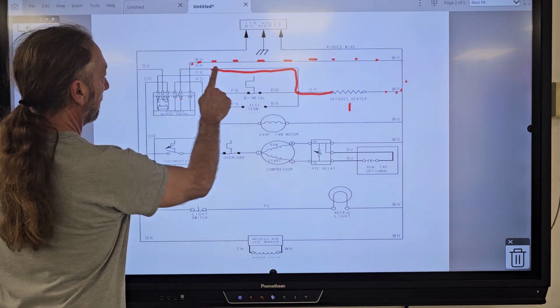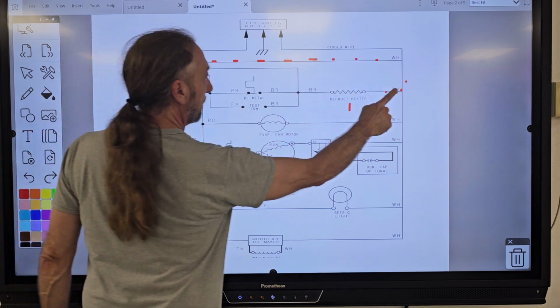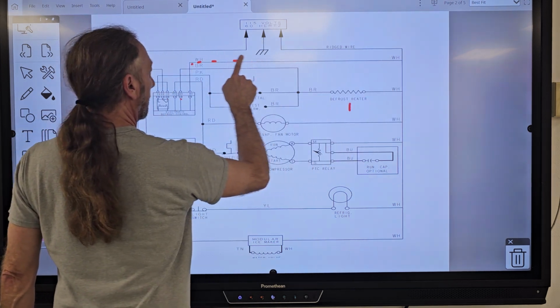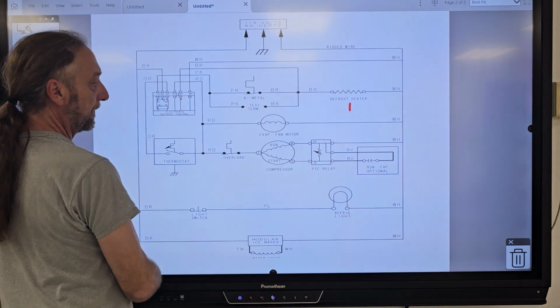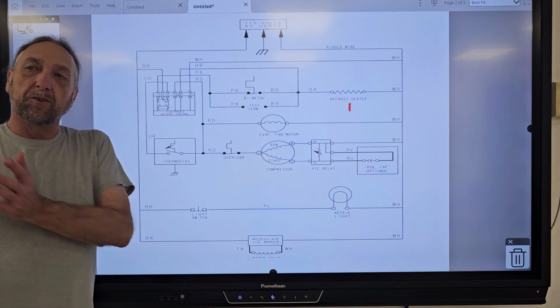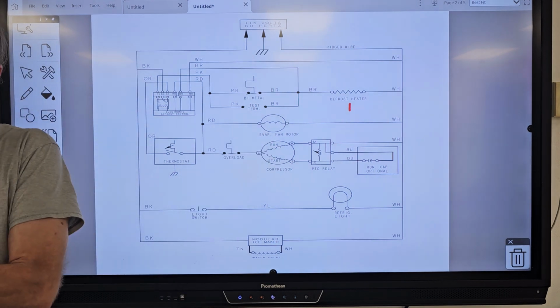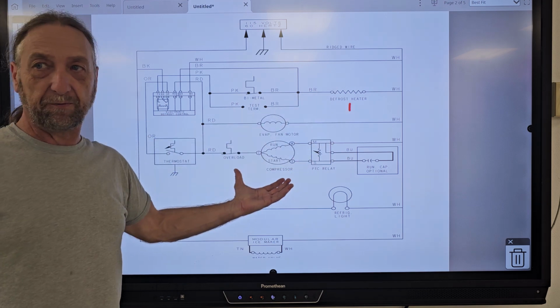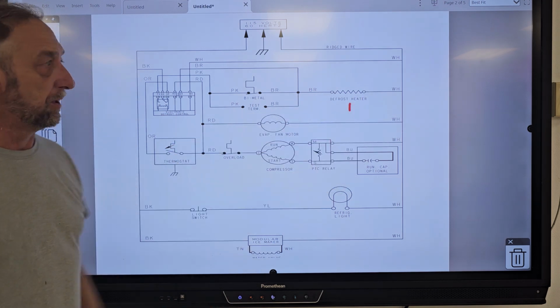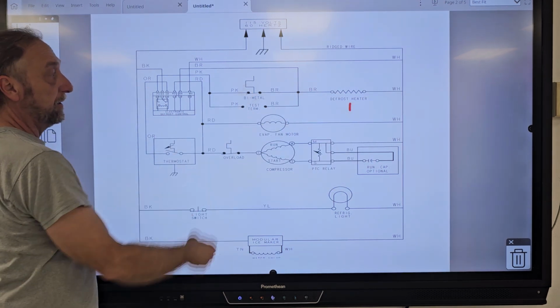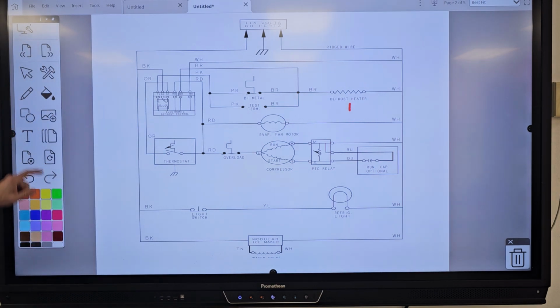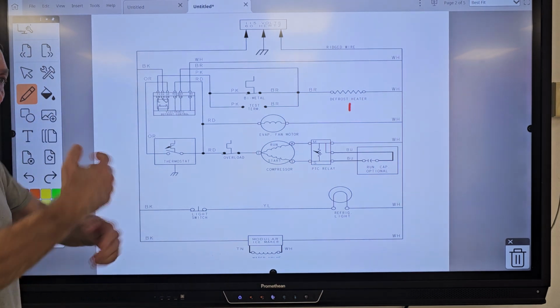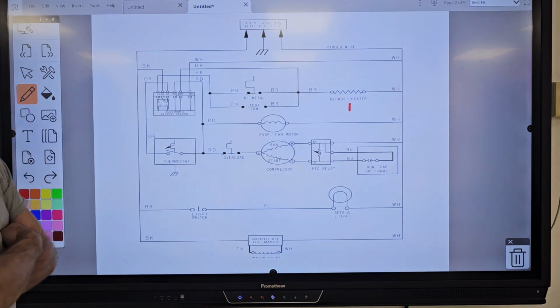Is it the fan? The evaporator fan? Fan has nothing to do with defrost. Well, we're saying the heater doesn't work, but I don't have voltage to the heater. So the fan doesn't send voltage to it, but we have a thermostat here, right? So where am I gonna put my meter now? Come on, man, where are you gonna put it? On the electronic defrost.